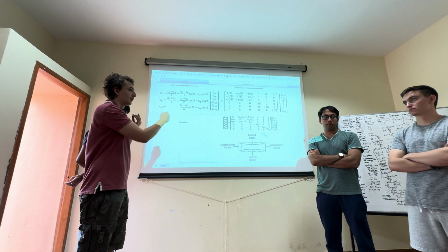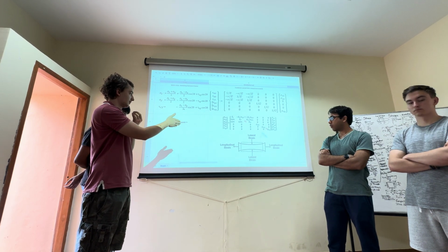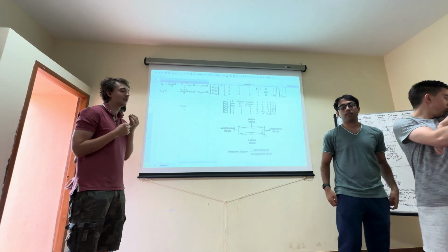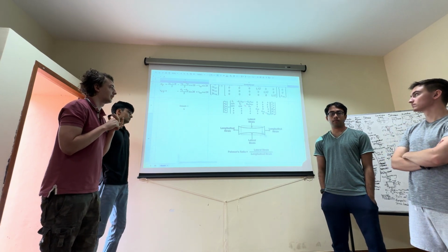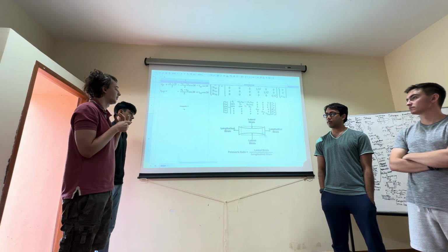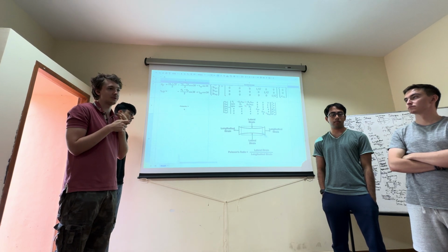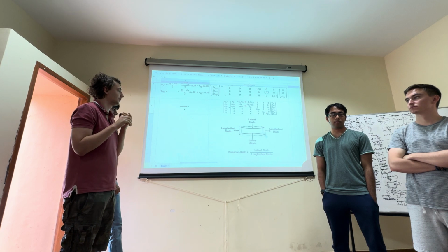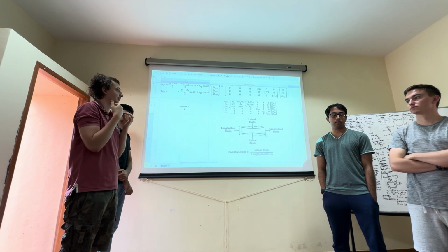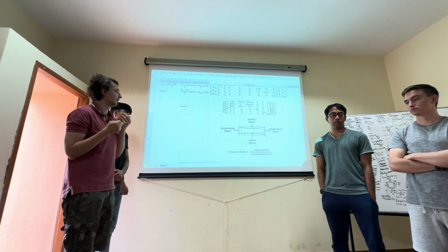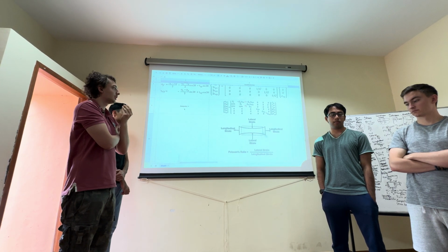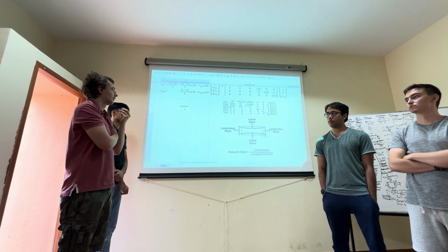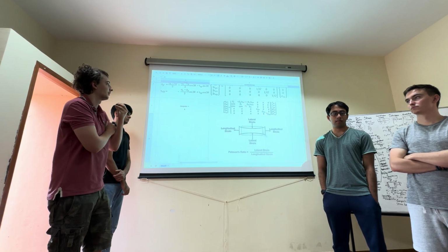Also we have Poisson's ratio. Can you do a bit there? Poisson's ratio basically relates the lateral strain and longitudinal strain, which also goes to the Poisson deformation in a way. That is, the cross-sectional area reduces if you pull on the material, and it can increase if you compress the material, as well as other shear and normal strains based on only one of the stresses.